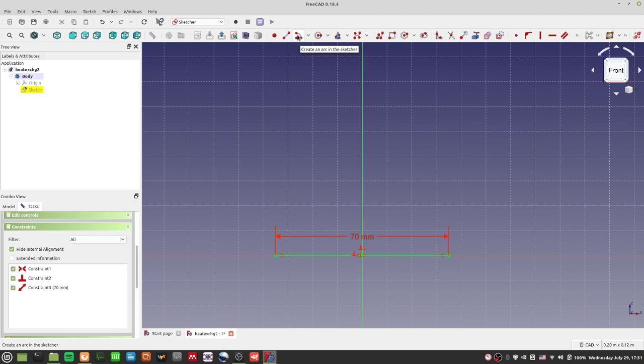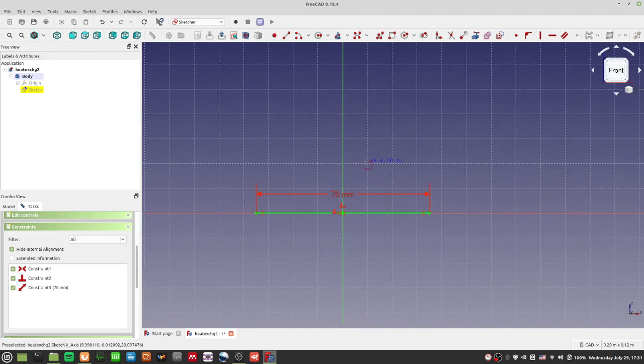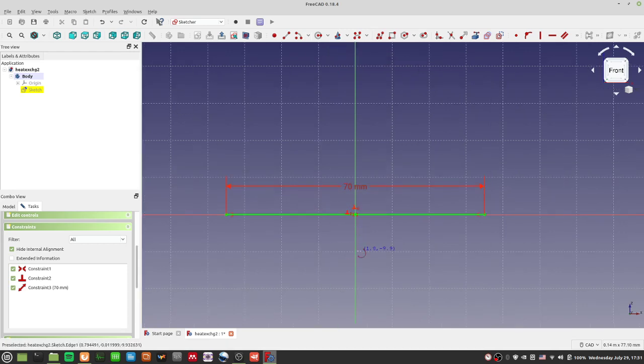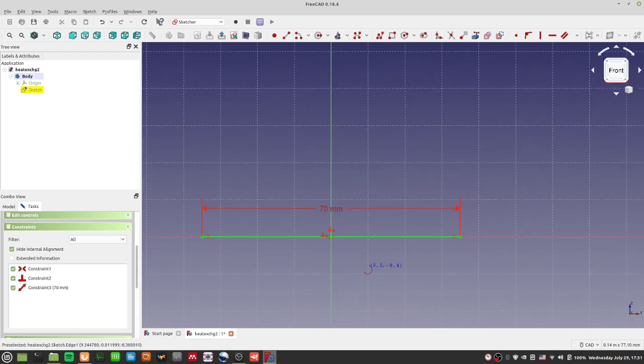Alright, so let's do so by first starting to create an arc. So what should your arc be like? They'll give you two options. You can either select the center and end points, or you can have the end point and rim point. I take the center and end points because to me it's easier. The first point will be your center, and the arc tool will be just nearby the line tool. You should know where the line tool is based on the last video.